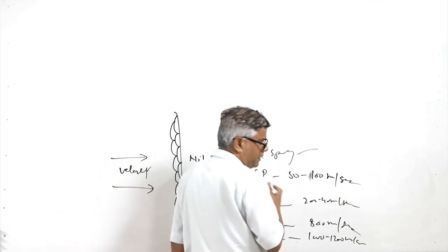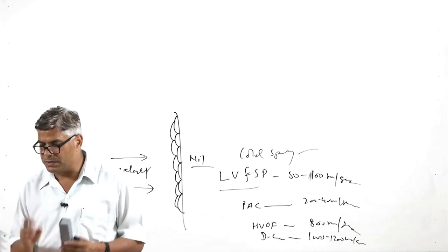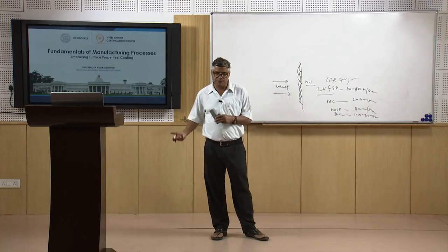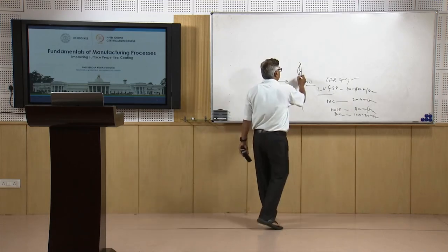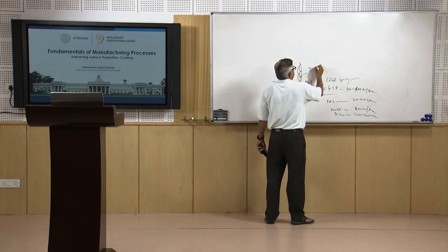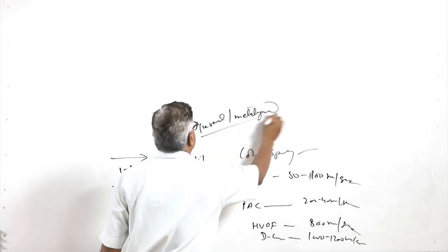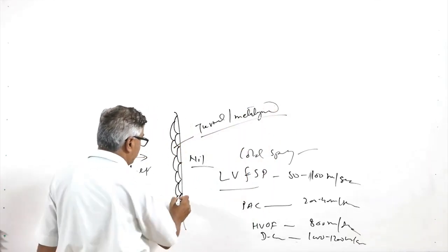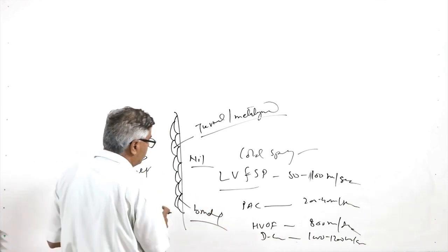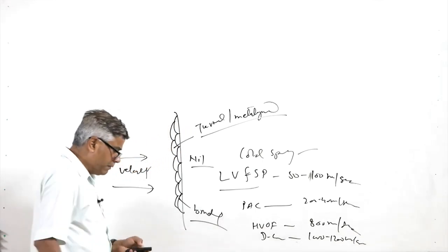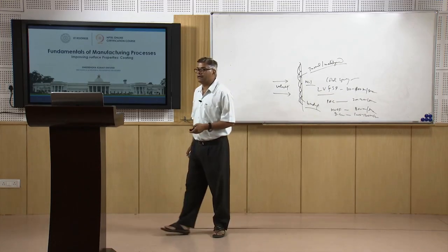As per the process, the peak temperature attained by the material in the course of heating and the velocity attained will vary, and these two things will determine up to what extent thermal or metallurgical degradation of the coating material takes place, and second, how firm the bonding is between the coating material and the substrate. So, it becomes important to see the different kinds of processes and their comparative study.